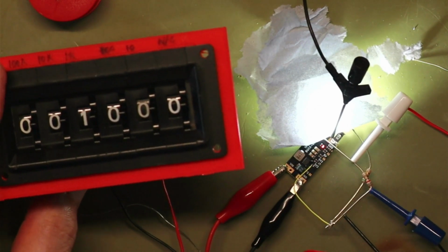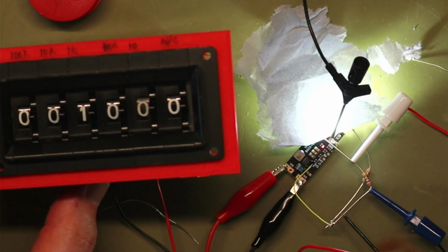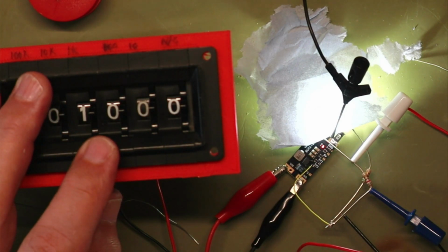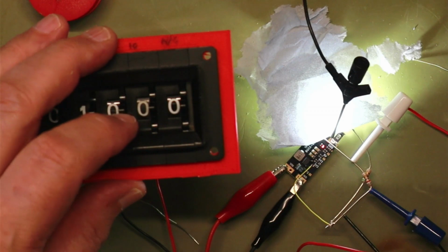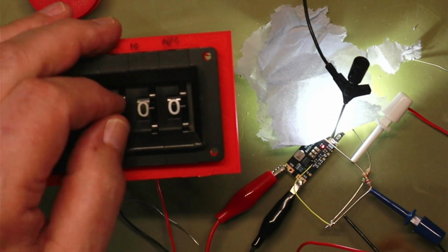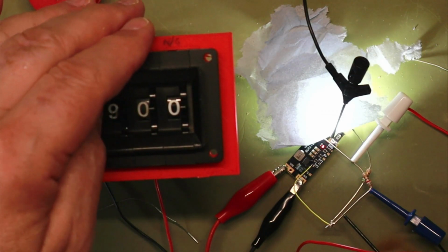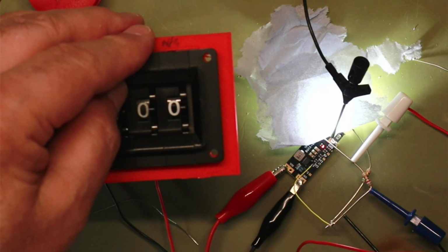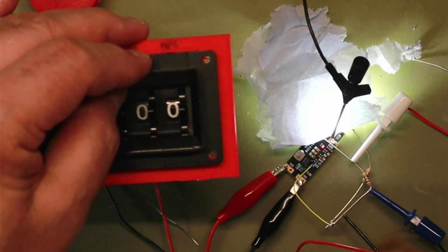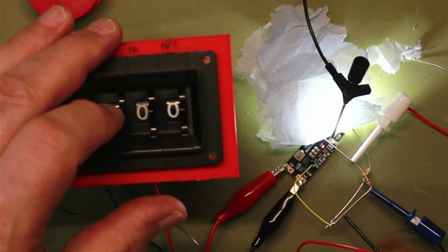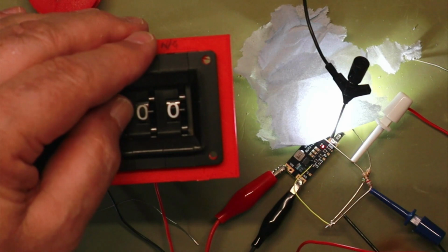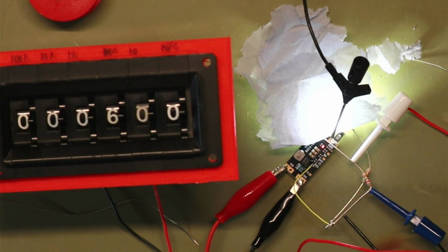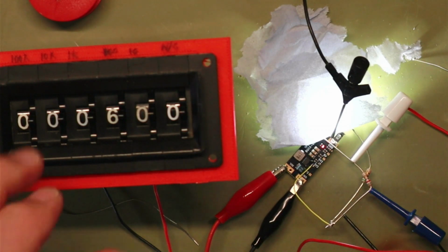That's with 1k in parallel with the 800. So if I want to go lower, then what I can do is put it up to 9, drop that, and then you'll see we're at half an amp now. Go down another notch. We're getting dimmer. As you can see, as I lower the resistor value, the current drops, and now we're at about 300 milliamps.